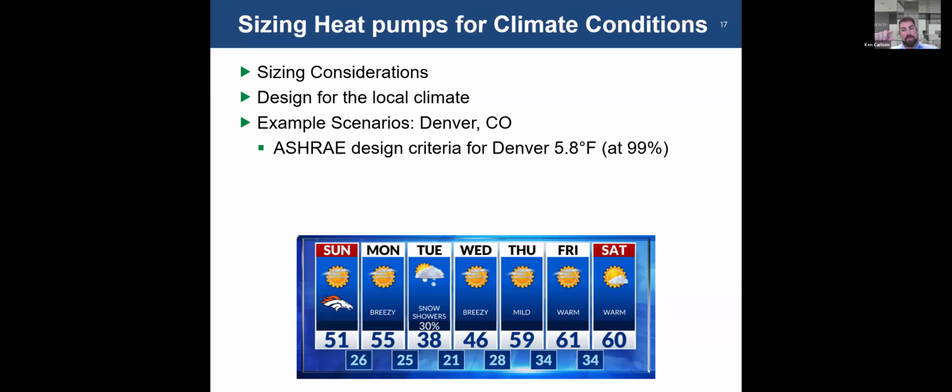The COP of a heat pump is typically above 3 above like 30 degrees or so, therefore being actually higher and more efficient and costing less than that posted value. So that value is really just an average COP. It's not necessarily accounting for every bin of data throughout the range, if that makes sense. So it's just a blended estimate. It's not accounting for all the low ambient resistive heat that you might need. But it's not overstating the COP either, just for clarity. The COP is typically 3.5, 3.7, 3.8 above 30 degrees.